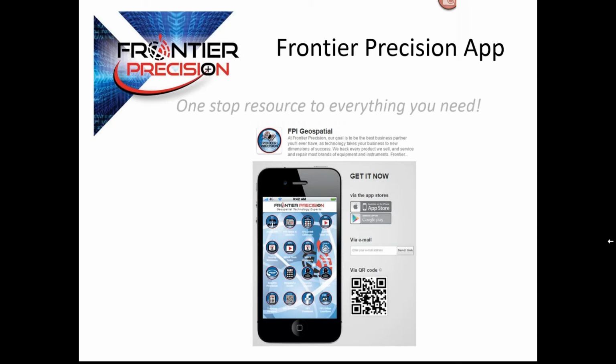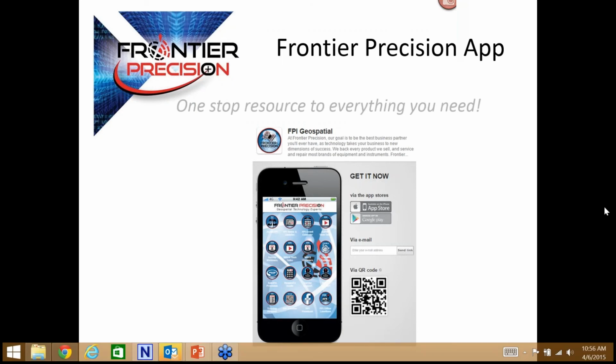That's just going to be just like a single base. It is no different, so I would expect that your accuracy should be the same. It's just a little bit of education. You can't just log into the VRS and expect to hit every vertical. It's just not going to happen. Just like if you set up your base on different positions every day, you're going to get a different position on your vertical control that you check into.